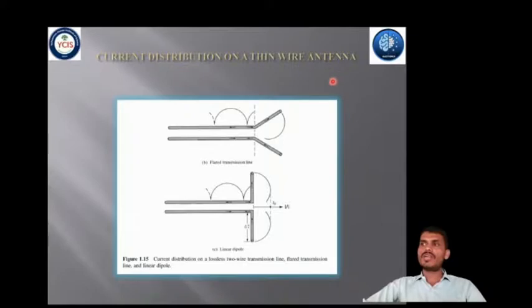However, because the two wires of the flared section are not close to each other, the fields radiated by one do not necessarily cancel those of the other. The field radiated by these two wires cannot be cancelled because the distance between them is very long. Therefore, ideally there is a net radiation by the transmission line.